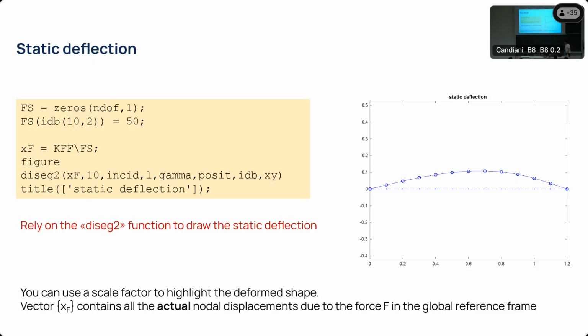This is also something that will be interesting for your assignment, at least to have a grasp on it. Let's try looking at how to implement the weight of the structure in this formulation, because you cannot just put a vector which has the weight of each of the elements for each of the coordinates, because remember that some coordinates will be affected by the weight, some others, of course, will not. So you can try thinking about how to implement the static deflection of a structure under its own weight.